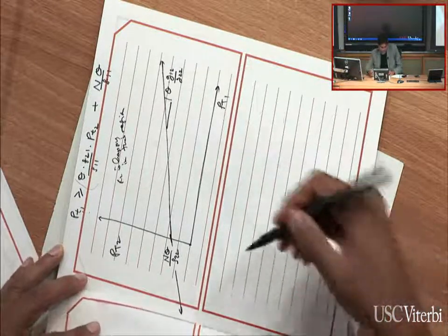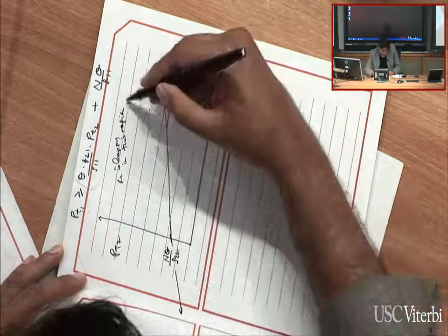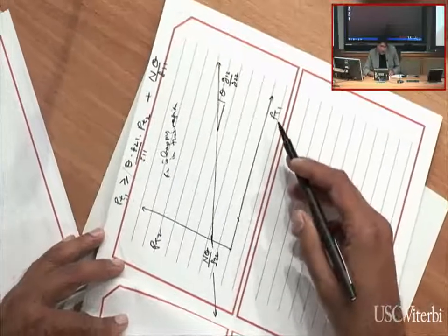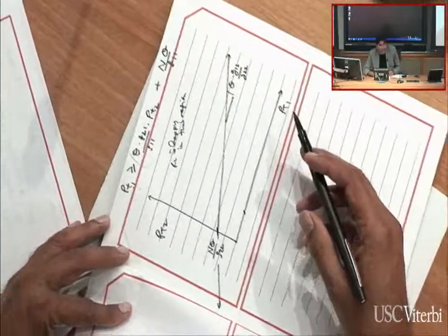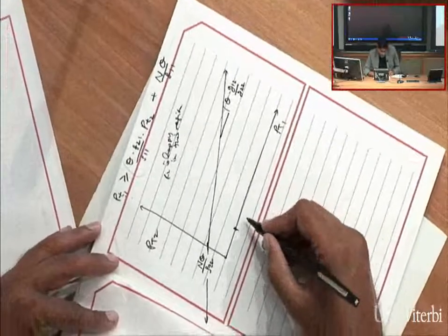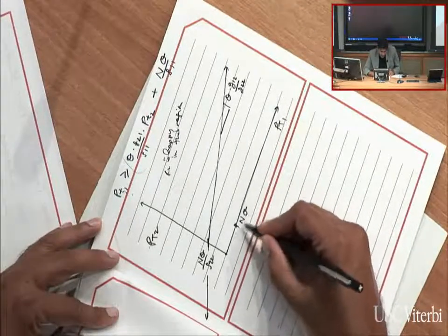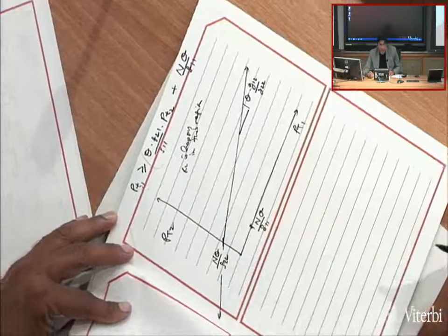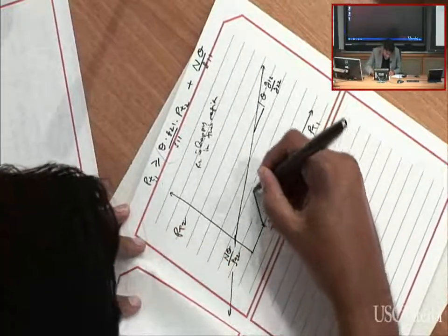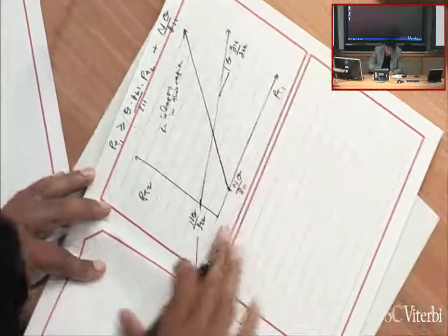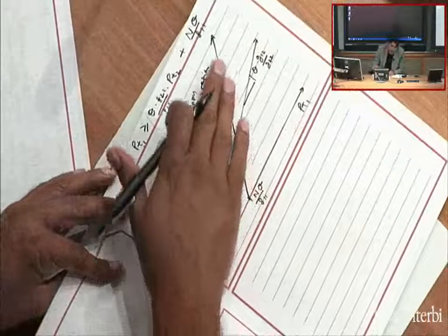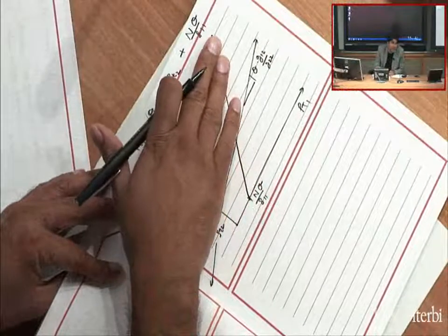And in this curve, it's the same idea. See, if there was no interferer, there'd be some power level at which PT1 would be high enough, which is the SNR would be above threshold. And so this point would be N theta over G11. And as I increase interference to it, there's going to be a need for the first transmitter to boost its power higher and higher to stay above threshold.